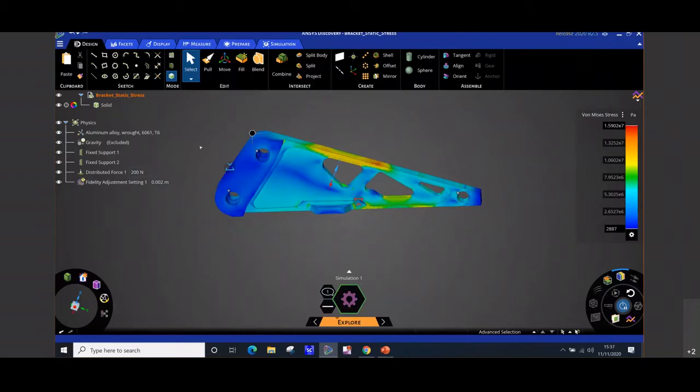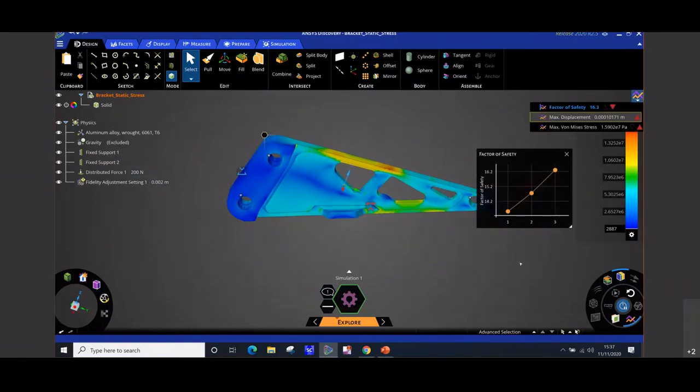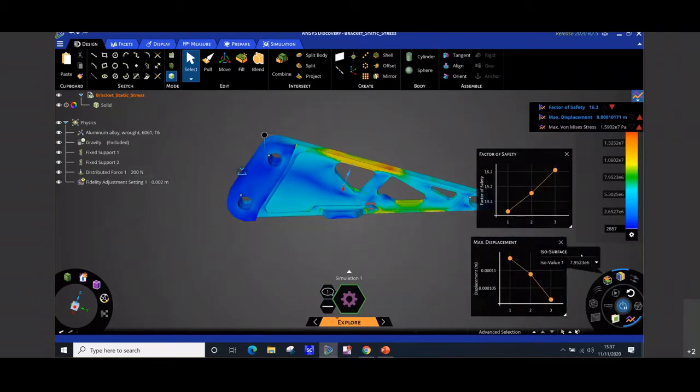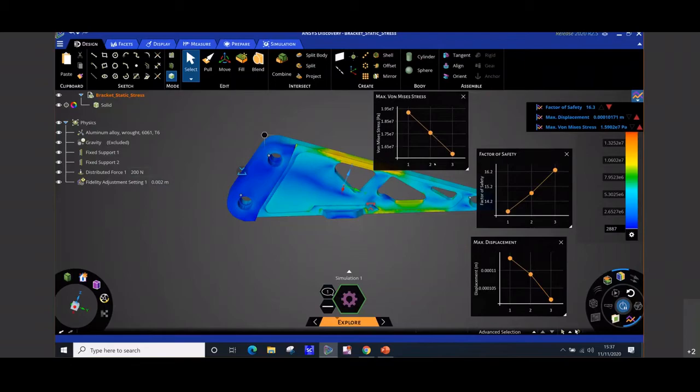And in this example, Tim, the monitors probably show those 3 changes you made. Yeah. So that's the factor of safety change from the first, second to third. And again, you just right click and show a chart there, and we can show what changes they make. And the last one is there. So each change is a different iteration, and you can see what effect that has from the first one to the third one. They can all be exported as well into tables.